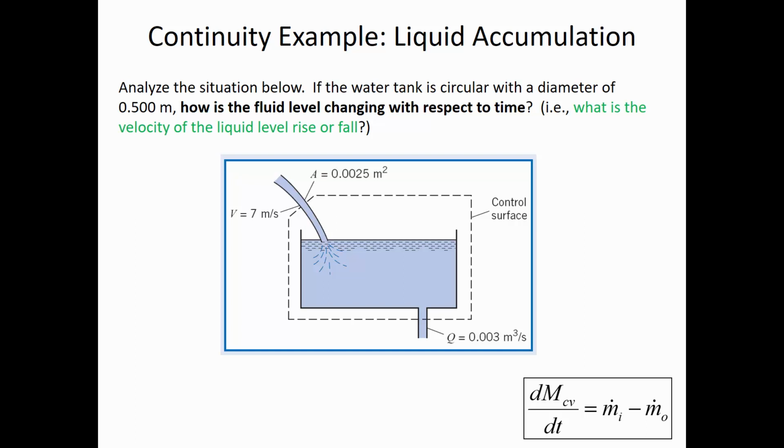So this is different than what we saw in the lab yesterday. In the lab yesterday we had a jet coming out, and the flow out of the jet depends on the liquid level height. The two clues that this isn't one of those problems is, number one, it's a pipe that's coming out. And so you can see that thick black line on either side of the liquid. If it was instead an orifice, then it would look like some streams or ripples, and there wouldn't be the thick black edge on the side.